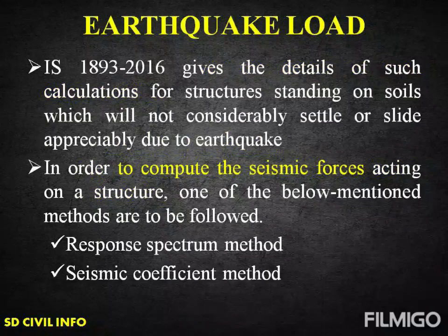And the IS code 1893-2016 gives the details of such calculation for structures standing on soils which will not considerably settle or slide appreciably due to earthquake. In order to compute the seismic forces acting on a structure, one of the below mentioned methods is to be followed. They are response spectrum method and seismic coefficient method.